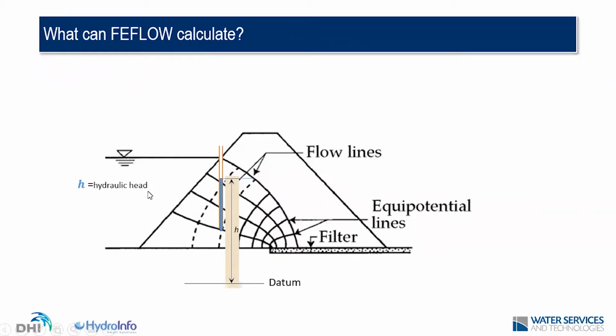So FEFLOW can calculate heads, but different from MODFLOW, for example, the FEFLOW formulation is not simply head. It actually considers that head is the sum of the gravitational energy given by the elevation plus the pressure energy given by pressure over rho g.